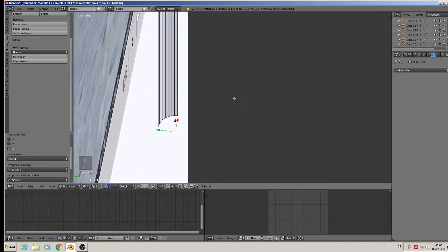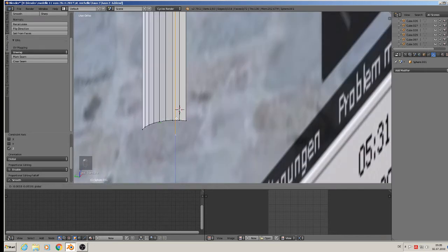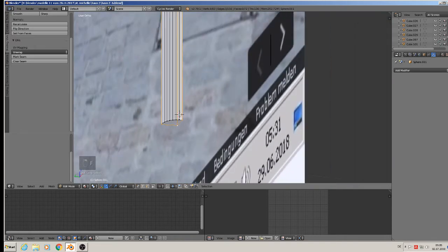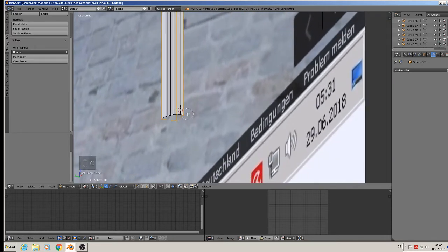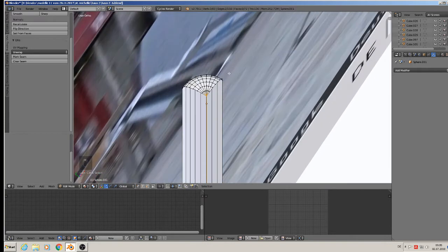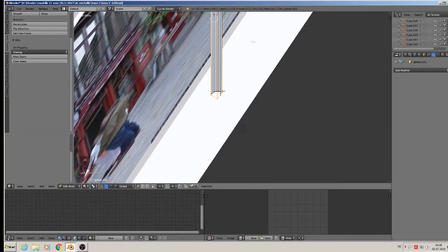Good. Now then we connect them before, so we connect them and close with F, and connect them and close with F. Then we take one of them, not the other. So C, circle selection, middle mouse wheel pressing, you can deactivate selected. So we can disable here that side, that we only close one side.